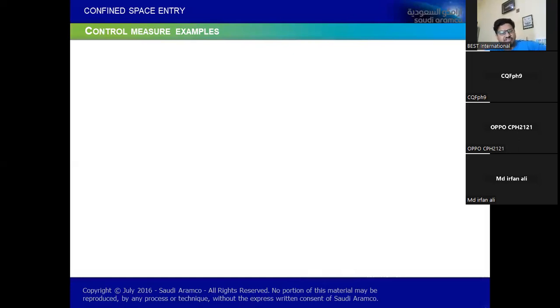Because they have to make sure, first of all, 0% LEL. Because above 0% LEL, hot work is not permitted. So that means the failure of isolation and LOTO procedure. Isolation and purging, also cleaning. Purging, exactly. They have not done. Absolutely right.